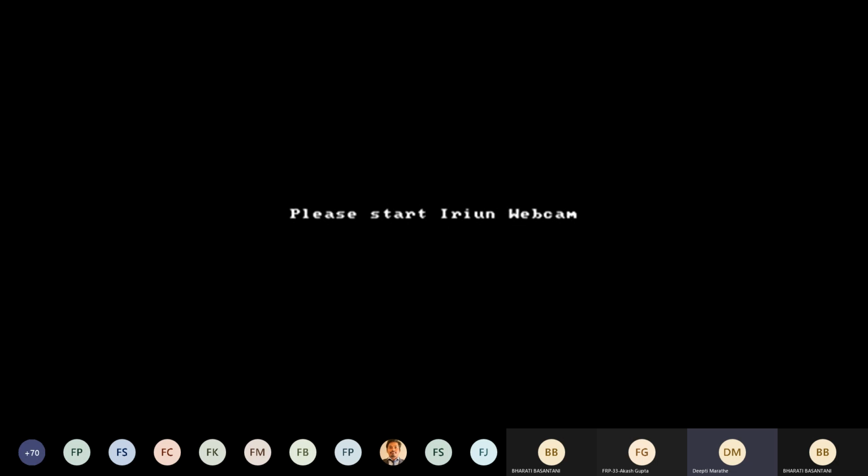Okay, ma'am. One more question I have. Ma'am, you're actually talking about the ply-by-ply laminate failure. Is it the same approach as a progressive damage analysis approach? Something similar to that. See, basically, when I was talking about 0/90 or a cross ply, it is a classic case because it is easy to understand, because we very well know that if I am going to apply load in the longitudinal direction, the 90 plies are the ones which are going to be weaker and which are going to fail first.